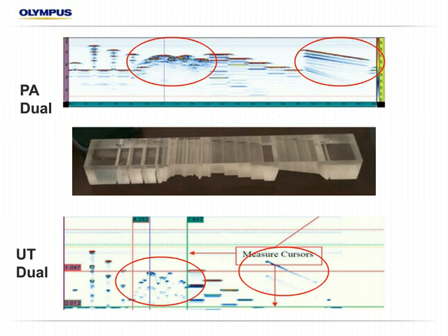With the PA dual, the DLA that I was just talking about, we basically take it out, select the file of the right thickness, change the material velocity to represent the block here, and move the gates a little bit, and with scanning we get very even, very good quality data of all the types of reflectors that we're looking for.